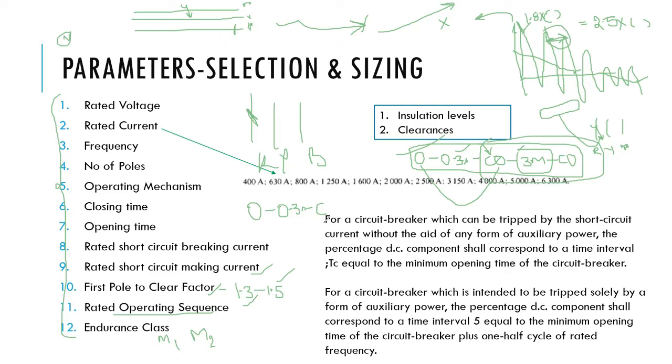Suppose my assumption was wrong. I made a wrong assumption. What will happen? The relay is still seeing the fault, and it will send the command to the breaker: no, it's a permanent fault, please open. Instantaneously, it is opening. And at the same time, it is operating the other two phases also, Y and B, with the concept of pole discrepancy.